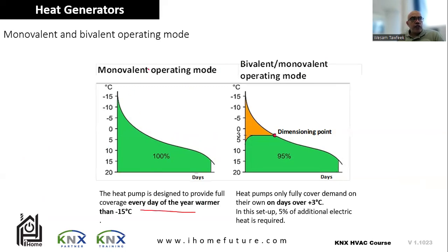If you are having a different system, bivalent, then normally you have an external or a secondary heat pump to give you extra power, because the first heat pump is not functioning all year with its full function. So when the heat pump is at full heating load, the temperature of the heat source should not fall below the planned limit condition. This is the normal way.